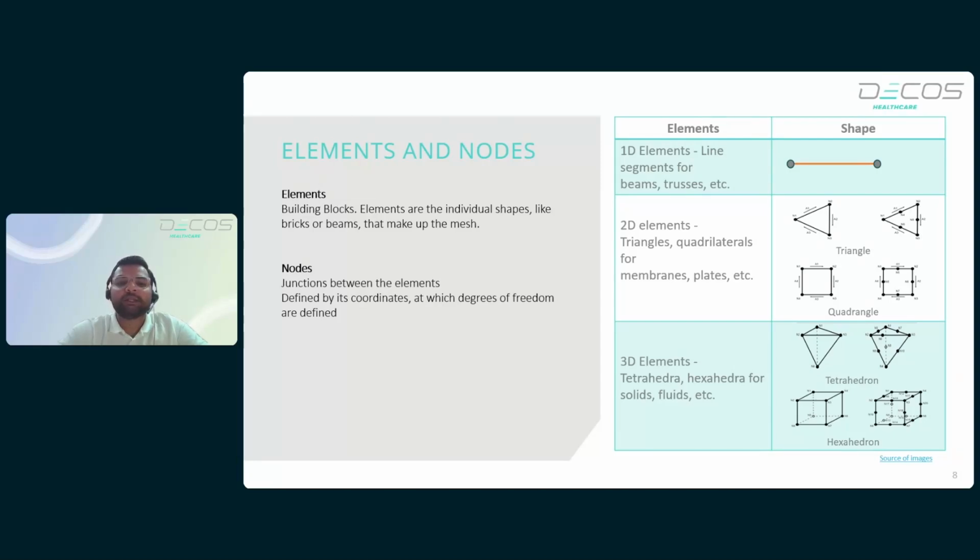Okay. Now, a 1D element can be a truss element or a beam element. Beam and truss elements are used for modeling slender structures like beams, columns, and cables. The difference between truss and beam elements is that beam elements are able to sustain or handle bending moments, while truss elements cannot. Okay. Fine. Now, let's discuss triangular elements or tetrahedron elements. If it is 2D it is a triangle, if it is 3D it is a tetrahedron or tet mesh, which is a commonly used word. Similarly, quadrilaterals and hexahedrons.